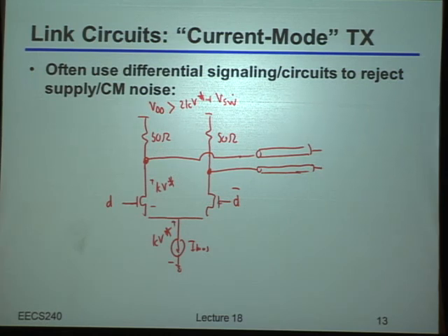The reason that's a little bit bad news is that, for example, if you were to compare it against a topology where you just made your power supply exactly whatever you wanted your swing to be, obviously you're paying extra power consumption. Basically, you have extra voltage overhead just to keep those transistors in saturation, as opposed to another topology where you just tried to have barely enough supply voltage for the swing you really needed. Make sense to everyone?